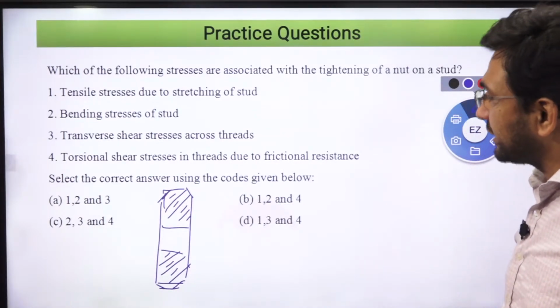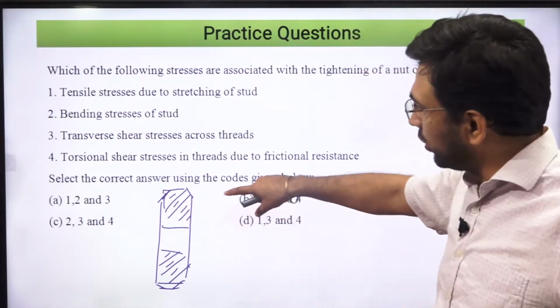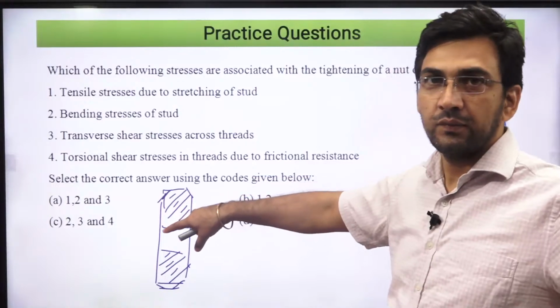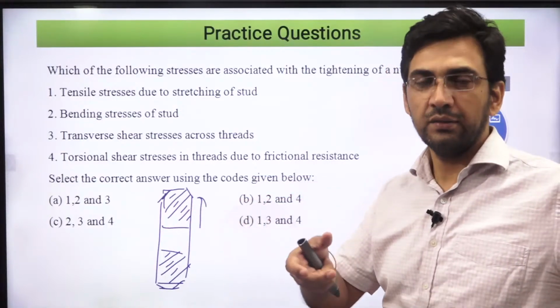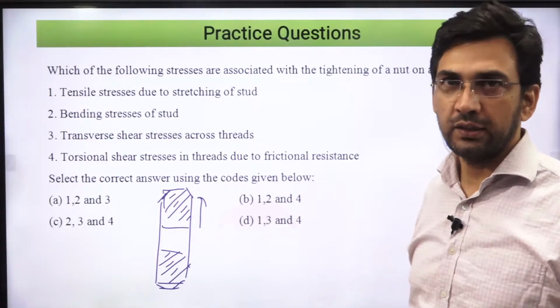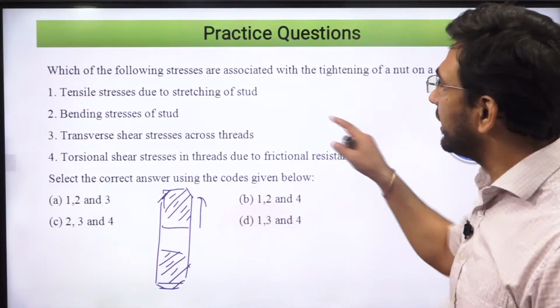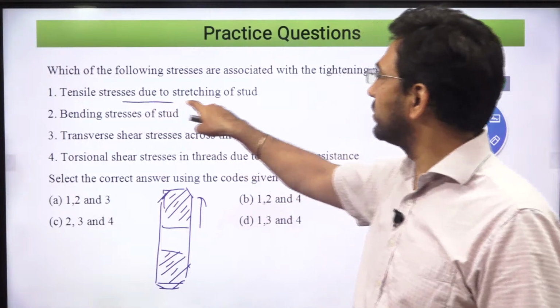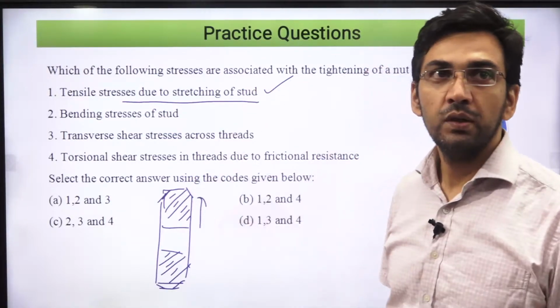Now obviously when you tighten the nut, what is going to happen? Tensile forces are going to be there, right? The same as bolt and nut, when you are tightening the nut, it is going to pull that bolt. The same is going to happen over here. So tensile stresses due to stretching of the stud, no issue, it will stretch.